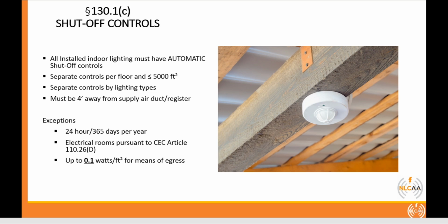So we kind of talked about this. Actually, we did talk about it. And we spoke about a space where you have two or more types of lighting. So if you've got general lighting and you've got accent lighting, and maybe you have a third one, which could be whiteboard lighting, those you need to control separately. To me, that is 3 zones.